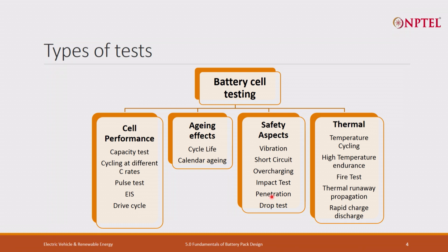And the last are the thermal tests. This consists of temperature cycling, which means cycling the cell at different ambient temperatures. Then high temperature endurance. We all know that lithium ion cells, when subjected to higher temperatures, can lead to thermal runaway.